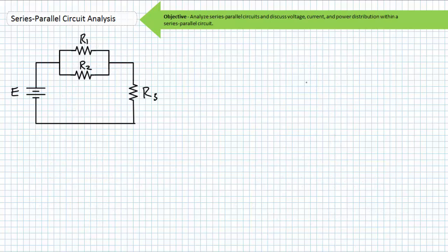Consider the simple utility of these basic series and basic parallel circuit properties when combined with the two-step process of visualizing the circuit from the perspective of flowing current and thinking about voltage at the nodal level. I'll start by assigning some nodes, A, B, and C. In this series parallel circuit, flowing source current, IS, enters node A and has a choice, either to travel through R1 or R2, splitting into two branches I'll call I1 and I2. The branch currents I1 and I2 recombine at node B. R1 and R2 are clearly in parallel with one another.